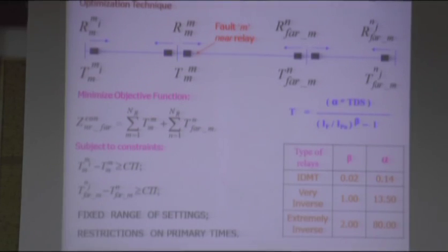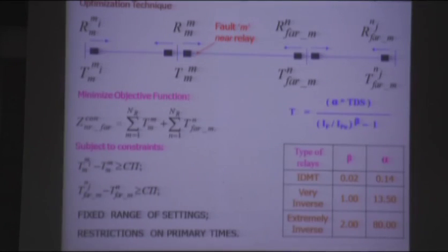Why are they required to operate? Because their direction of fault current is towards the bus incoming. Okay. So this is the primary and backup protection. Now backup protection is supposed to come into the picture only when the primary relay fails to trip. That means we have to give sufficient time to the primary relay to operate.